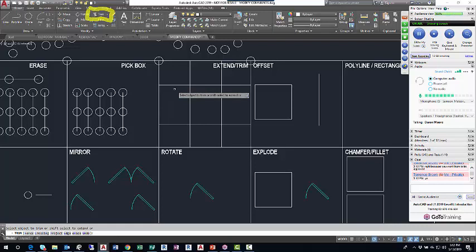now is not an extension to a boundary. It's being trimmed back to a boundary. I hover and I left click. I trim back to my nearest boundary. Hover, left click. Hover, left click. So the preview now is that line fades out. There's a little red X at my crosshairs.